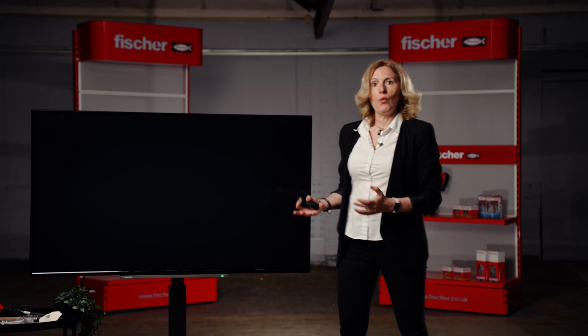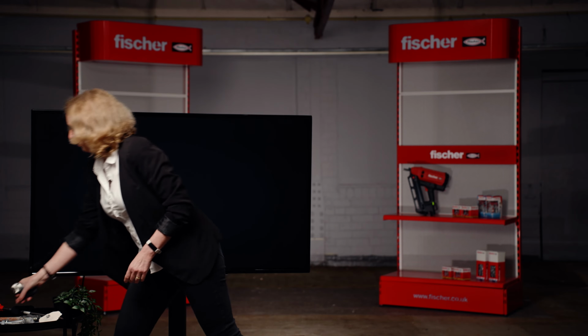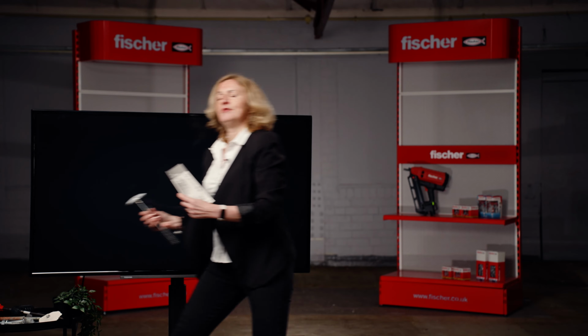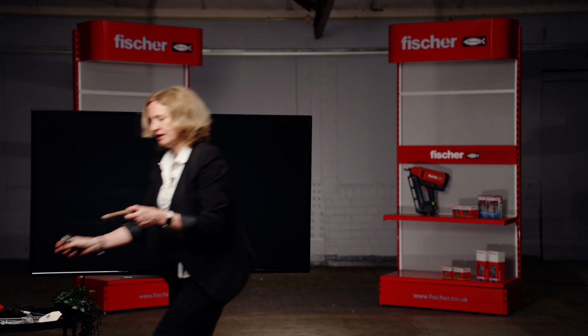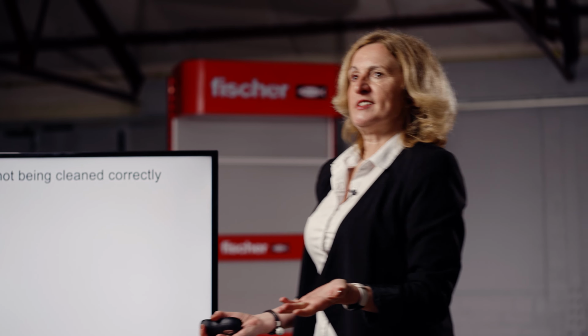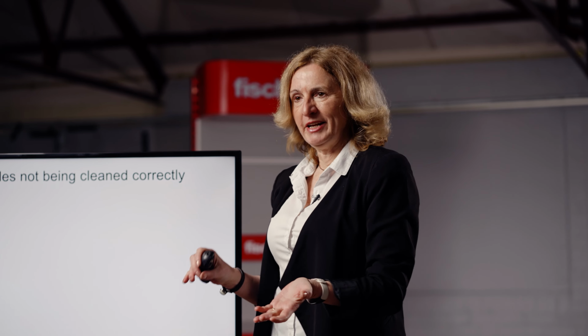So the video showed why it is important to clean a hole correctly, to use correct installation accessories, a blowout pump, and also a metal brush. We provide guidance on how to install the anchors correctly in the installation leaflet we supply with the resin cartridge. And here you see an example of a resin anchor which was pulled out. If you're a designer, you can actually eliminate this risk.